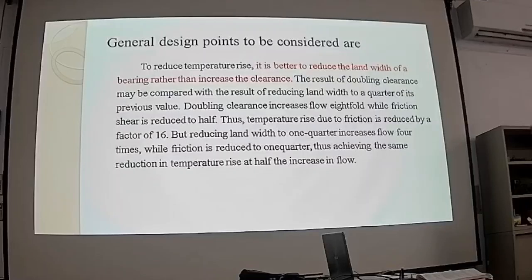Here is the first one. In order to reduce the temperature rise, it's better to reduce the length of the bearing rather than increase the clearance. Because if you reduce the length, you can reduce the bearing land area.